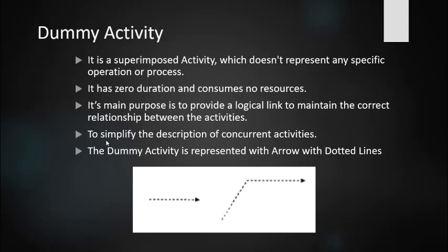By then the reinforcement bar bending is also going on simultaneously. If these two are completed, then only you can construct the foundation. You have to complete these two activities, the excavation and the bar bending, and then only can you pour the concrete for the foundation. The foundation work is the corresponding third activity.